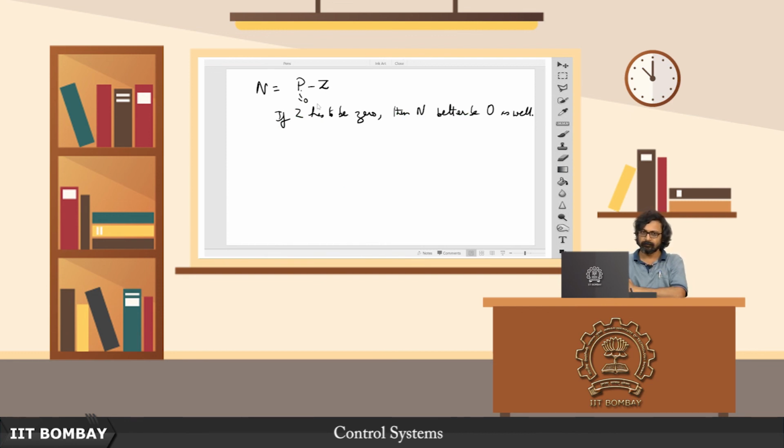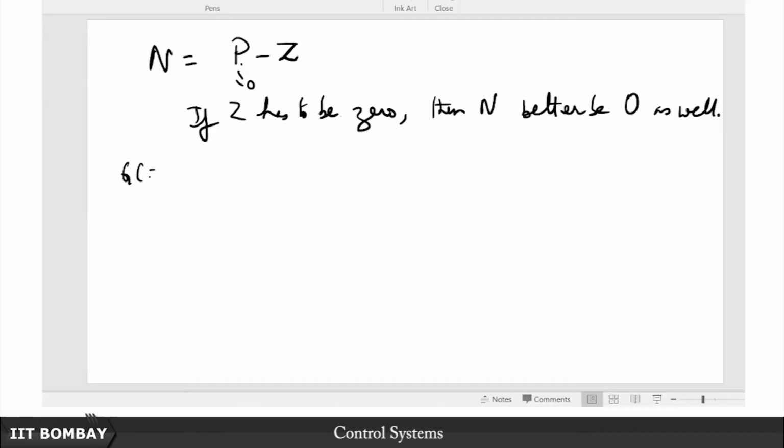So based on this understanding we shall now venture into comparing between these notions of gain margin and phase margin as we understand based on Bode plot and say Nyquist plot. So what we will take is a typical transfer function, the one that we are very familiar with. Let us take GC equal to some k upon (S plus A) into (S plus B) into (S plus C).